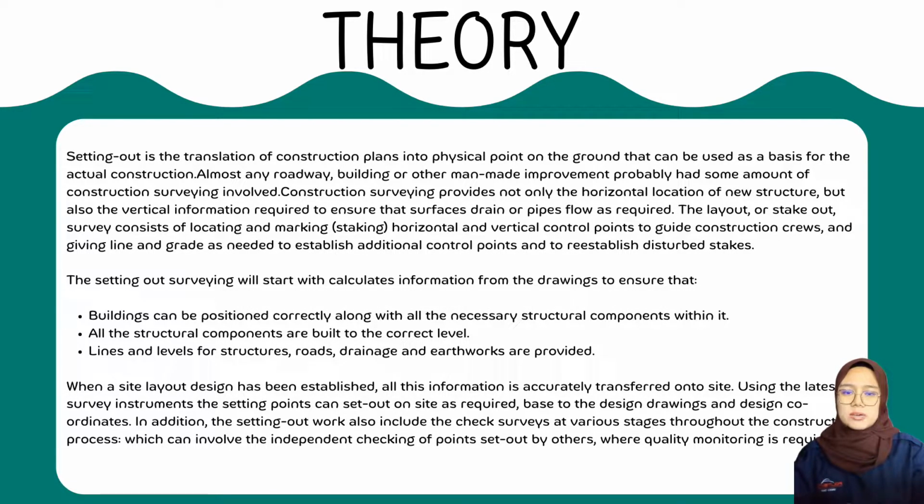Next, when the site layout design has been established, all this information is accurately transferred onto site. Using the latest survey instruments, the setting out points can be set up on site as required, based on the design drawings and design coordinates. In addition, the setting out will also include check surveys at various stages throughout the construction process, which can involve the independent checking of points set out by others where quality monitoring is required.